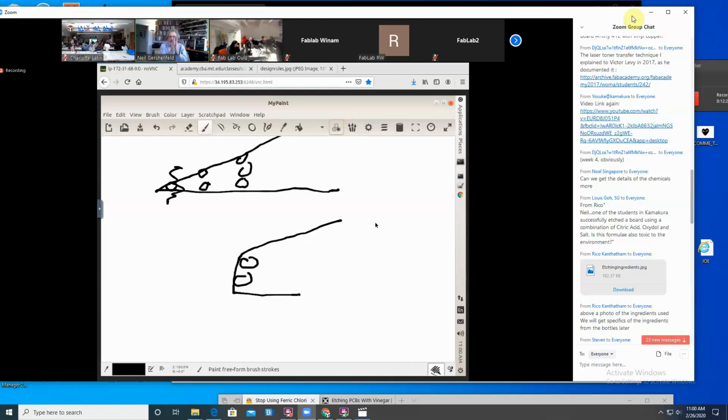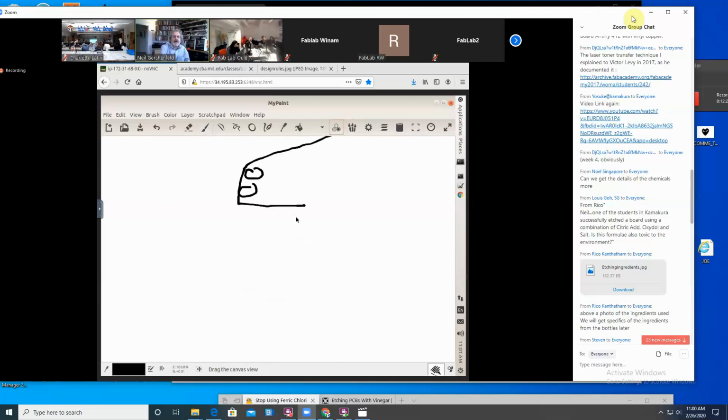You don't want to design walls that are too thin. You don't want walls that are too close. You don't want to go out over an overhang and stop. You either want to bridge between supports or have a slope.